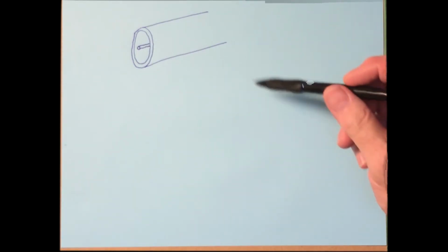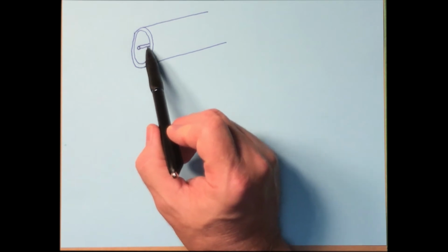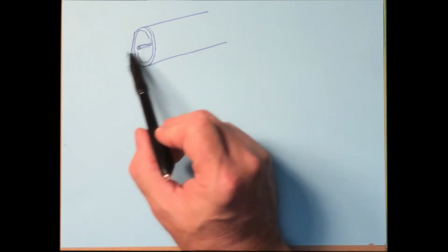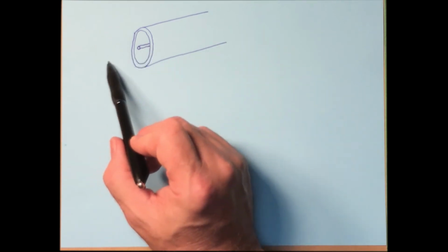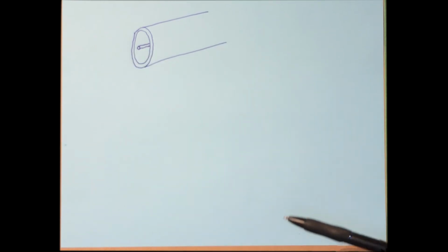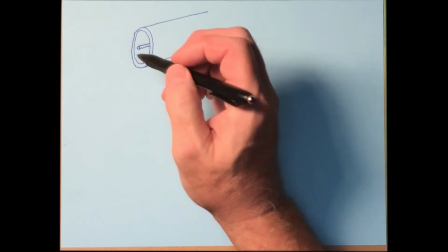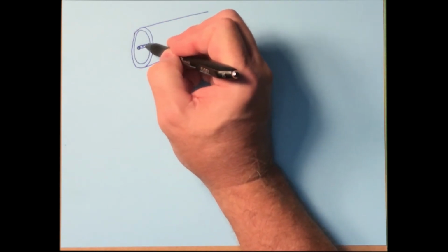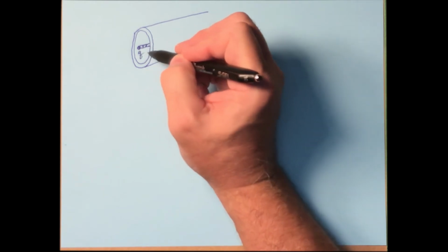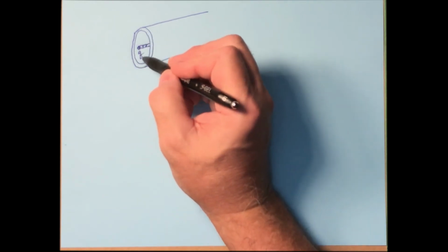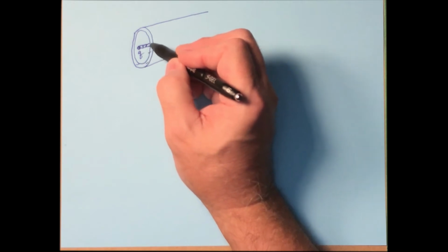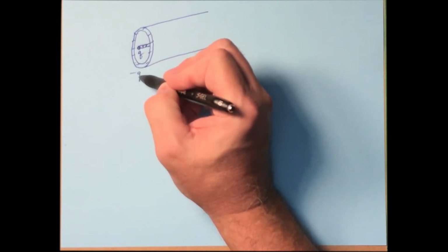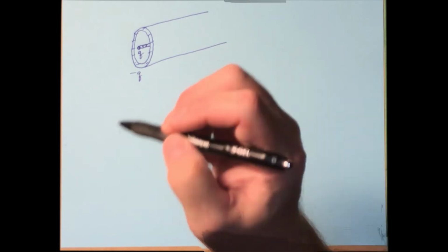This is called a coaxial cable because the axis of the center conductor and the axis of the exterior are on top of each other, so they share the same axis, so it's coaxial. Let's say we have a positive charge, plus Q, on that center conductor, and we'll have the equivalent on the outer conductor, but negative. So we have minus Q on the outside, like that.